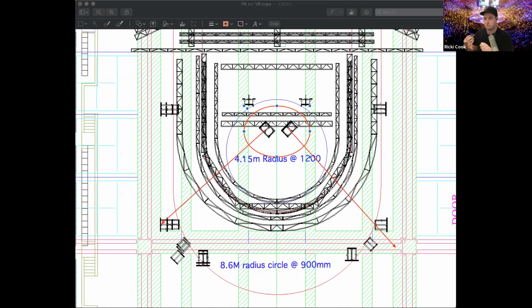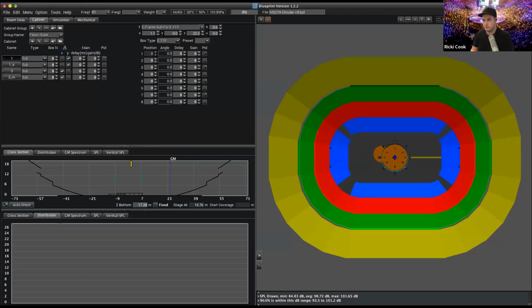Put some music, put some content on that you're really familiar with, and more or less start making sure that system's balanced. Now, if it's in a small environment and you're adjusting things at the DSP, or even an analog processor, if it's just a crossover, you can pull things back by 1 or 2 dB, 3 dB even, and you'll be fine.